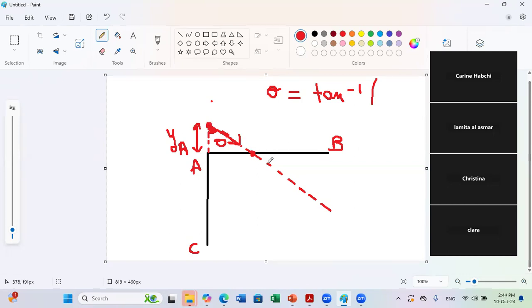Because when you displace a force along its line of action, its moment about A will remain the same. Why will it remain the same? Because the perpendicular distance from A to the force will not change. And if you put the force here on AB, since you have the same force magnitude, the distance from A to this line will always be D, so you will get exactly the same moment. That's why we say if we know one point of application for the single force, we can deduce infinite other points. But here, practically, we need a point on the structure.